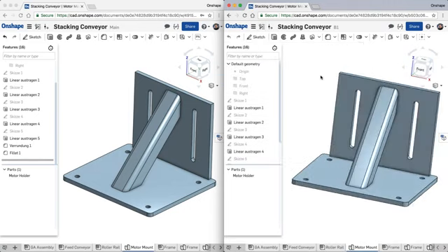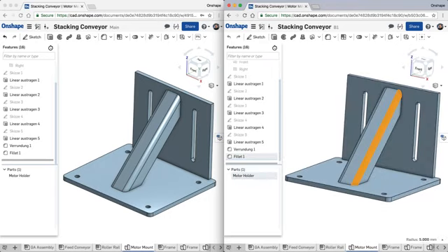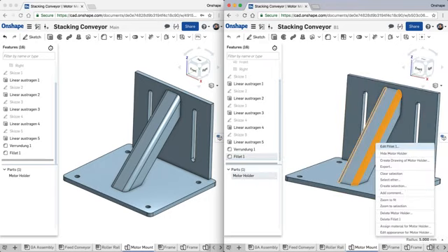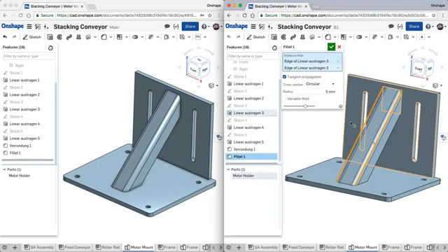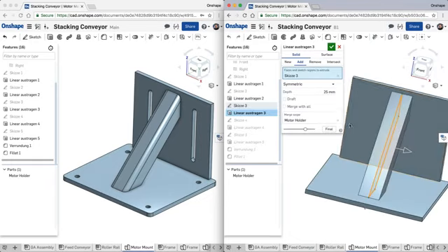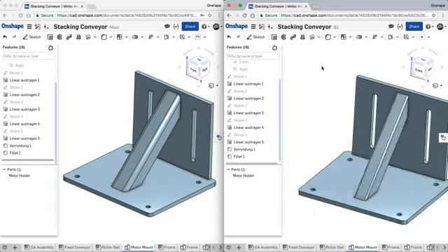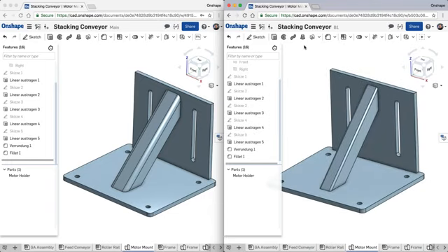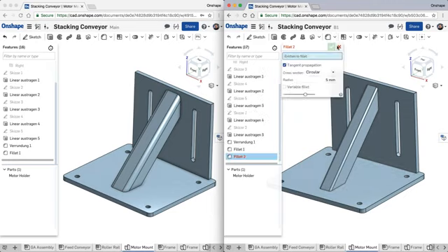So, for example, here now, as I start to come in, let's edit those fillets there, and we'll make that say 2 millimeters, and let's make this thing a bit thinner. Yeah, something like that. I'm just making these design changes up as I go along. Perhaps add some chamfers on the edges.